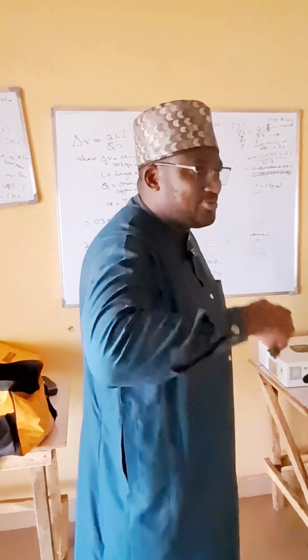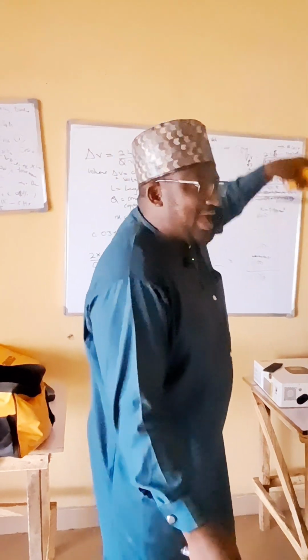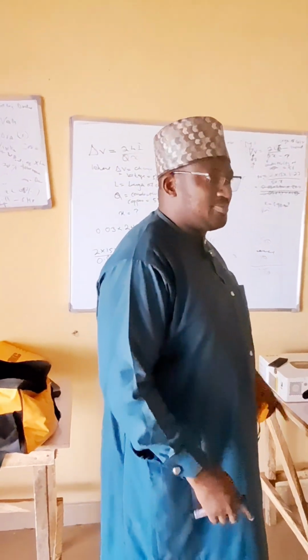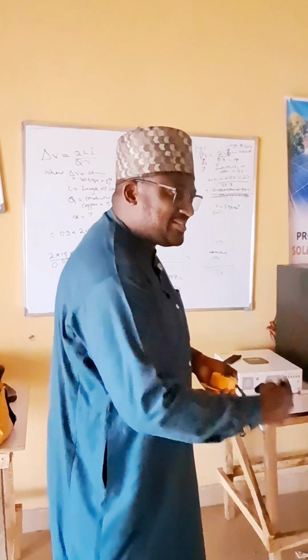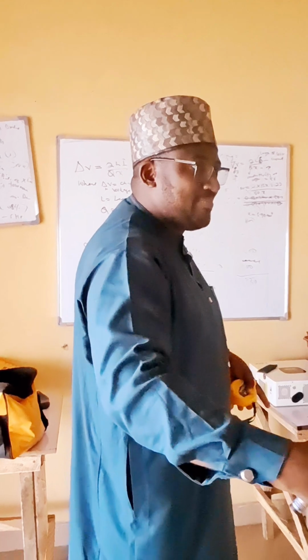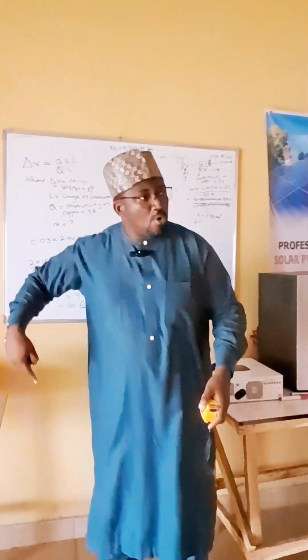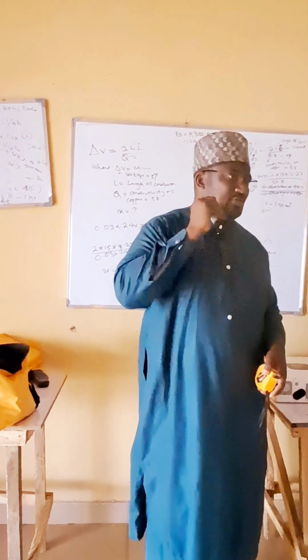that is why I said, of course, you have to get to the rooftop before mounting the solar panel. So you measure the area where you are going to mount the solar panel and take note of that distance. And then from the roof downward, you can take 10 meters, so 10 meters plus the distance where you connect your panels. You sum them. You also have to connect the battery to the charge controller and then the inverter.